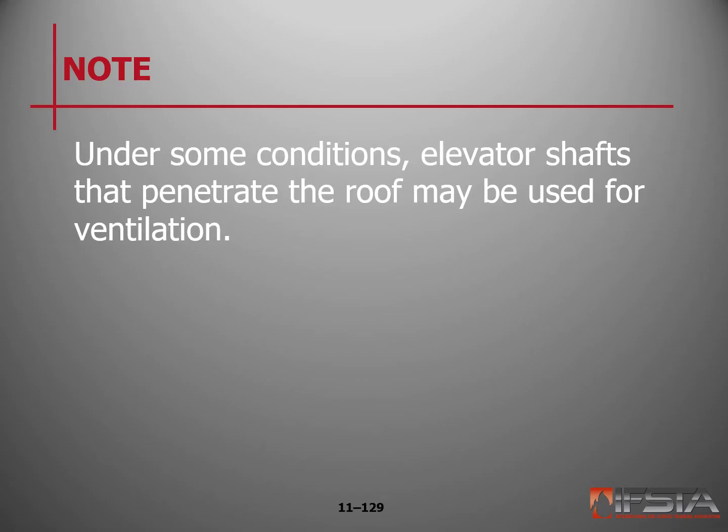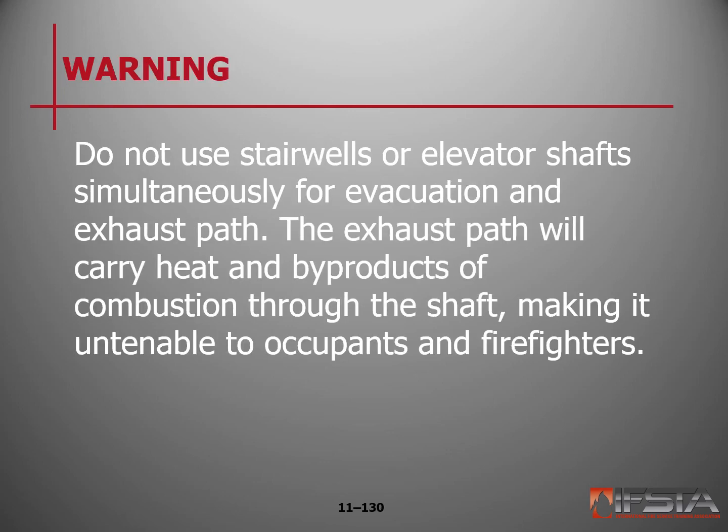Under some conditions, elevator shafts that penetrate the roof may be used for ventilation. Do not use stairwells or elevator shafts simultaneously for evacuation and exhaust path. The exhaust path will carry heat and byproducts of combustion through the shaft, making it untenable to occupants and firefighters. Makes sense.